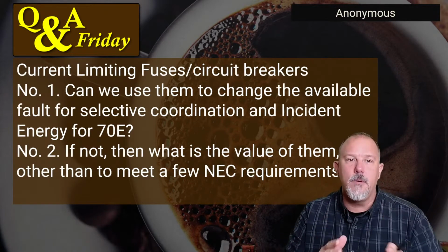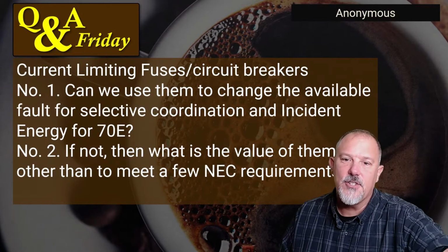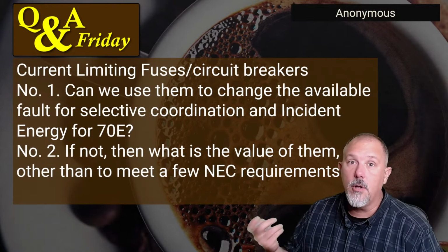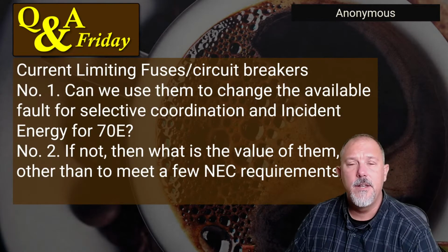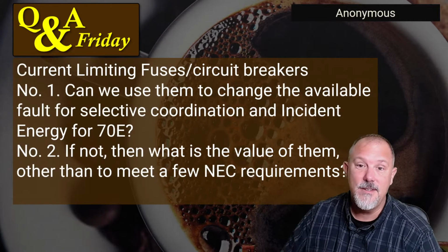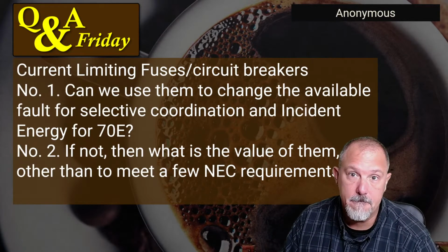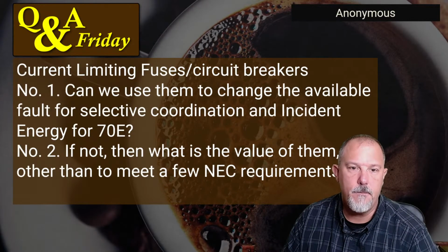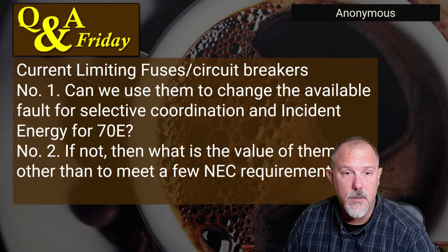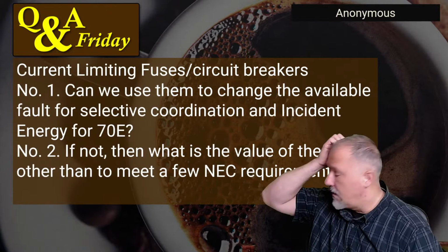And that's a very valid point, because here's what happens when an event like that occurs, and there was no damage. The pushback you get is, boy, look how much I have to replace those fuses, and they're expensive. But if they did not open, you would probably have had to replace equipment, or you could have killed somebody. So the incident energy reduction and the avoidance of replacing equipment or sending somebody to a hospital is worth that expense.